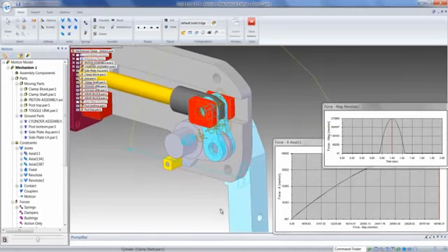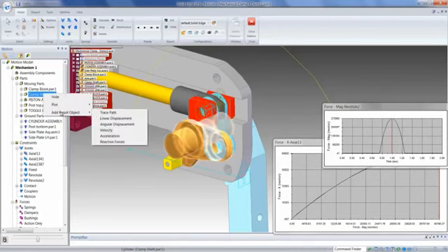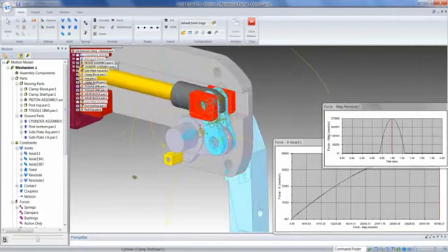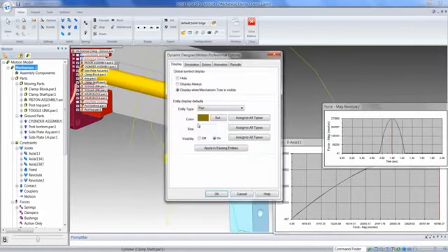Additionally, as we did for the clamp pad, we can also plot the load vectors for the clamp shaft part to visually verify the directions of our loads. Simply right-click on the clamp shaft, add result object, reaction forces. To help get a better visual of those forces, we can do two things. The first is we can change the color of the force graphics.